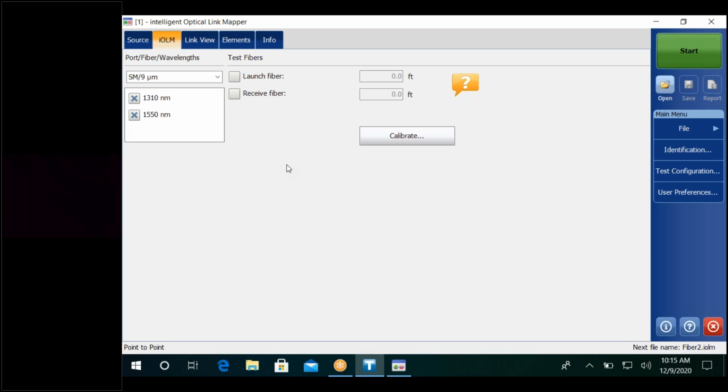This is OTDR that's automated. This is OTDR that has intelligence. There are algorithms built into this program. Again, it's a separate application that works like OTDR. We don't want to ever confuse it and say it changes OTDR. As users, you have the ability to have iOLM and OTDR on your machine, so you can have both applications.